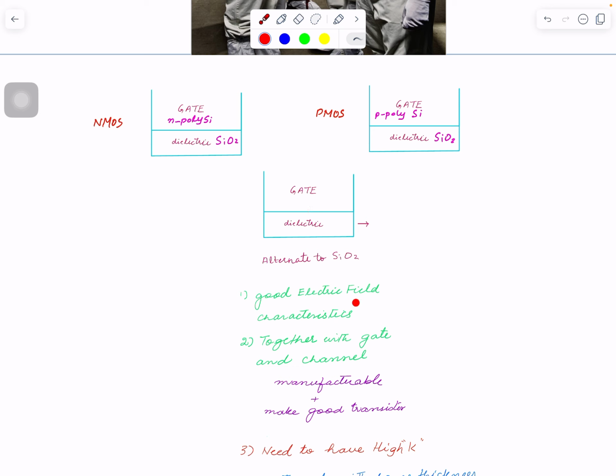The other thing is, eventually this thing needs to be manufactured, in very large quantity. So when you put that dielectric here and that polysilicon gate over here, they should work together. It's not okay if on its own it has very good characteristics, but when you put a gate with it and a channel underneath, it doesn't work. It needs to first give, on the previous technology, the same characteristics that Intel had with the 65 nanometer, but then we are able to control it such that it gives additional performance. So it shouldn't slow down the channel, it should have increased electric fields there.